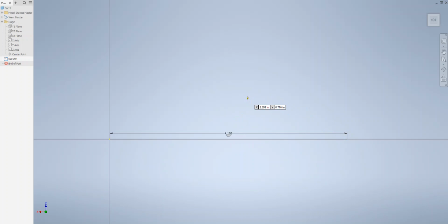And next, I want to draw a square. Again, this is going to be a construction line. It's not going to be an actual line. To do that, I'm starting from pretty much the same point, with a rectangle. The length of the rectangle is going to be pretty much the same, 4.12. The height of the rectangle is 0.53, so I'm typing 0.53.